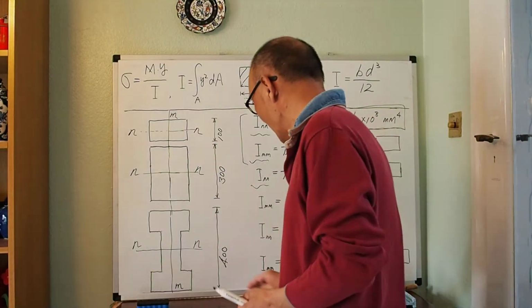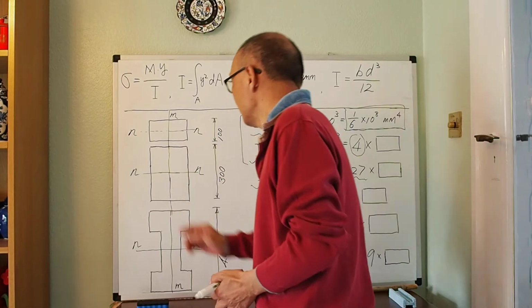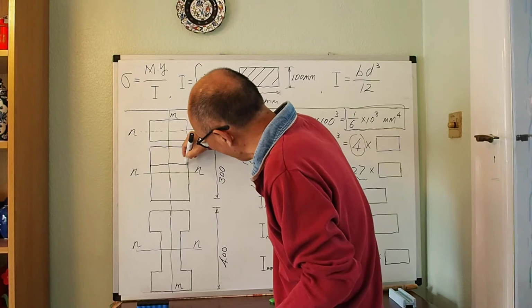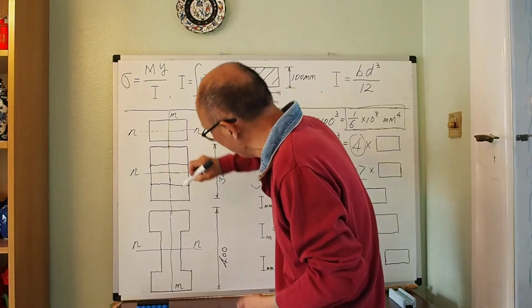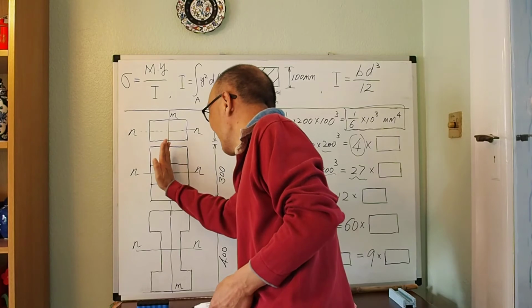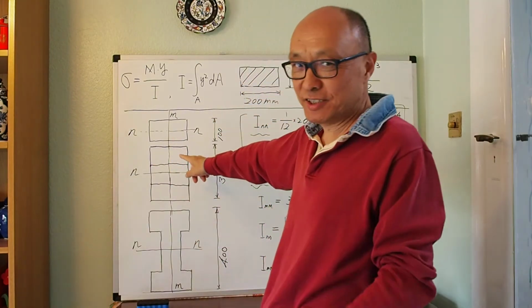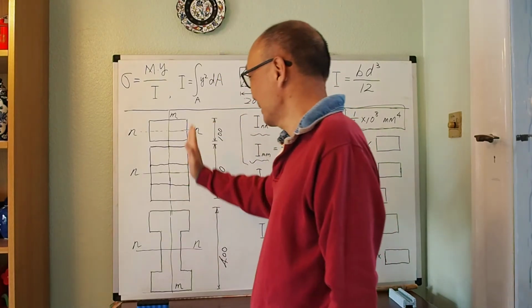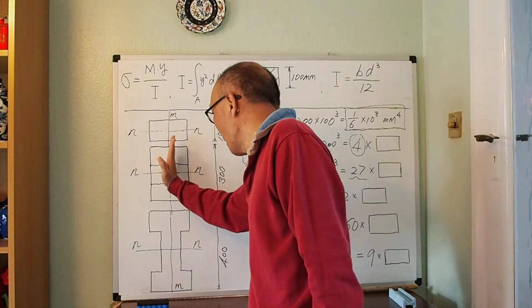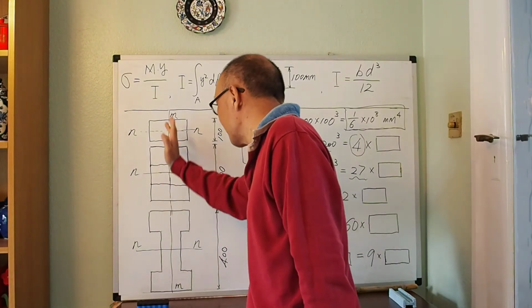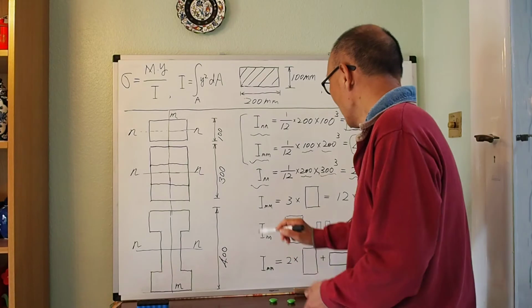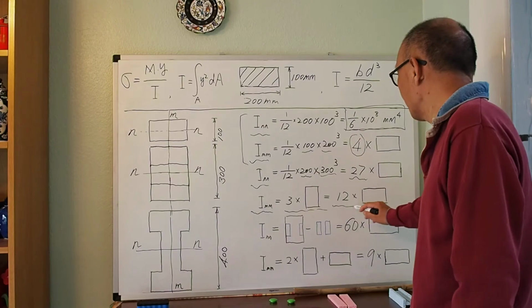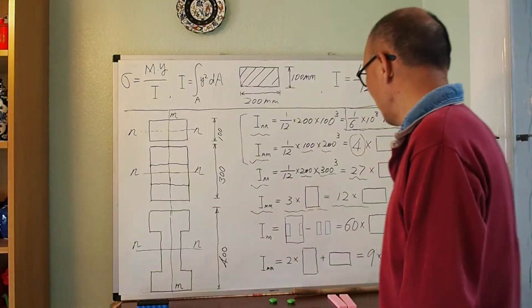But if I'm using my beam in that direction, and you can argue, and that is simply if I can draw this 3 section there. So if the beam bends about MM, this is just effectively 3 of this. Yeah, because each individual one still bends about the same neutral plane. So in that case, I_MM is just 3 times that, which is 3 times this case.